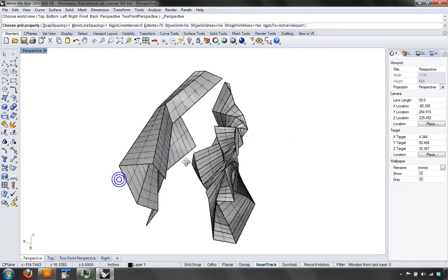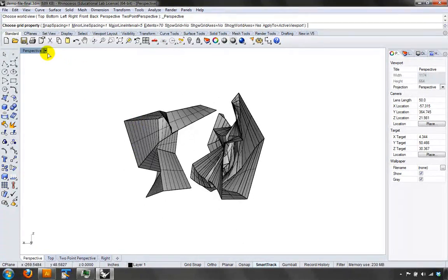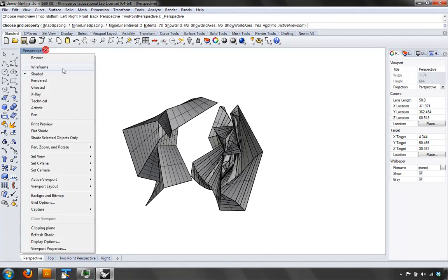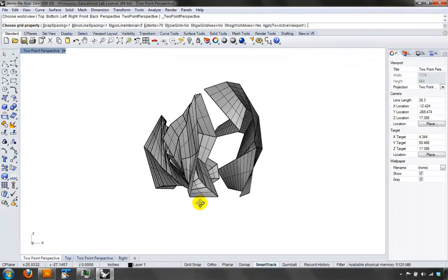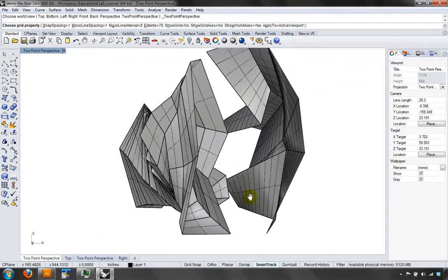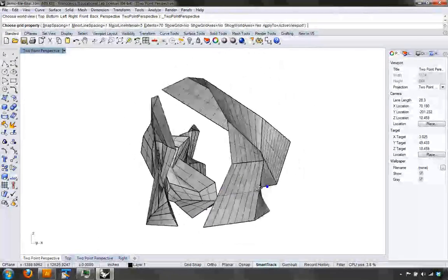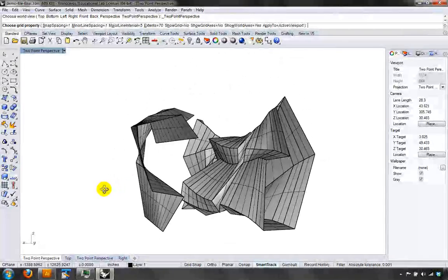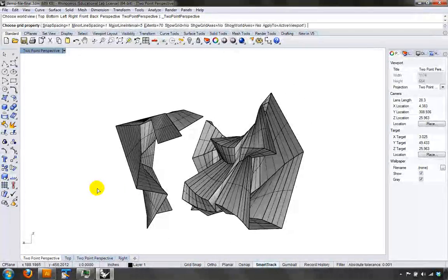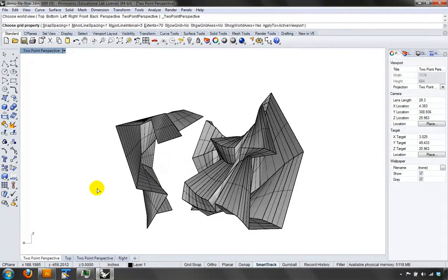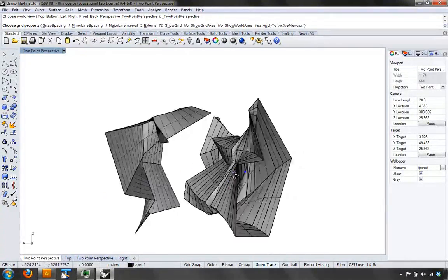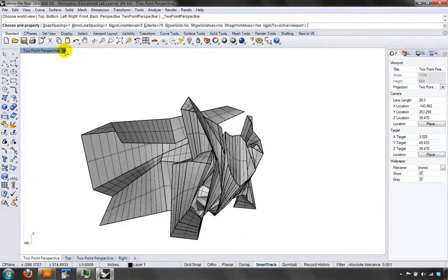to make the screen captures that you need to basically show your professor on Wednesday what your surface is about. You can use the perspective view. You can use the 2-point perspective view, which might give you more of a sense of the ground. I know we turned off the ground. You may want to leave the grid on just so that you get a sense of where the ground is. It's really helpful when you're doing this to have your scale figure vectorized so that you can use those outlines as a reference for the human scale of your surface.